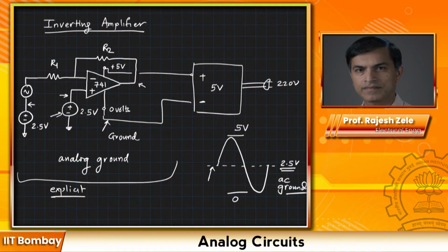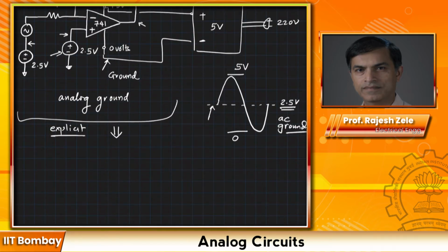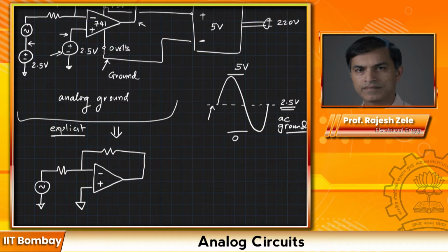However, this is very cumbersome to draw every time. So as analog designers, we like to simplify things with certain things assumed. And so I would simplify this schematic to something like this. And you can immediately see the difference. We won't show the supply voltage anymore. And here I would show my AC ground, and then I would show VAC or Vin. This is an AC source. Okay, so this is R1 and R2. So this is the simplified circuit that we like to draw.